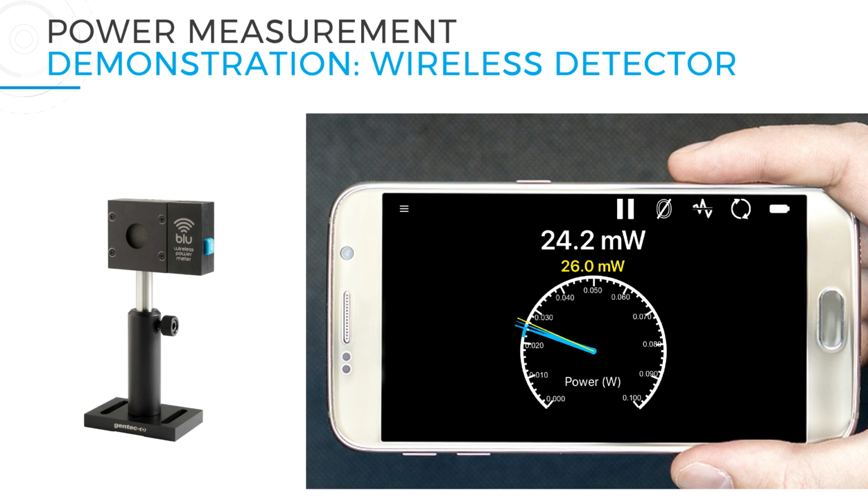Why? This laser is battery powered and I just plugged it in for recharge, so I did expect a slightly higher output power than with the photodiode detector. There's a lot of things going on that can affect laser power at the output. Also, the noise equivalent power coming from this detector alone here, the Thermopile, not talking about the background noise from the environment, the noise equivalent power from the detector, it's 1 milliwatt with such a Thermopile. Therefore, the fast fluctuations in measurements that you saw at this low power level. And by the way, this probe is rated up to 15 watts, so that can be used for higher power applications.